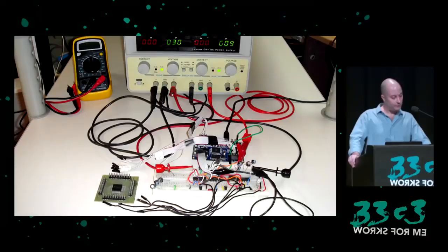My glitcher design is quite simple. It's based on an XMega development board and breadboard. I use the XMega to communicate with the ACP over SPI and to control the glitch. A 74 series 4053 analog switch is used to quickly switch the ACP VCC between two voltages, a normal operating voltage and a lower glitch voltage. I use a benchtop DC power supply and two outputs, so I can easily adjust both the normal VCC and glitch VCC levels. Other parts on the breadboard are an oscillator to provide some clock inputs necessary for the ACP to operate, and an inverter and NAND gate to cut out the clock during the time of the glitch.